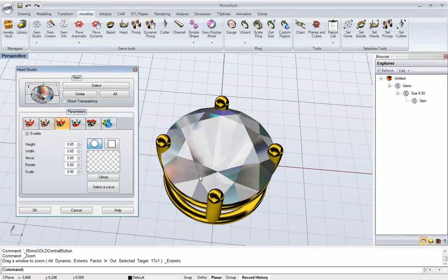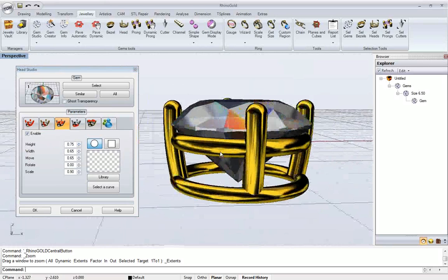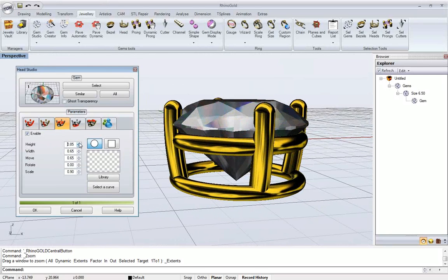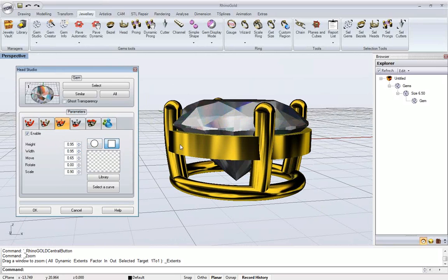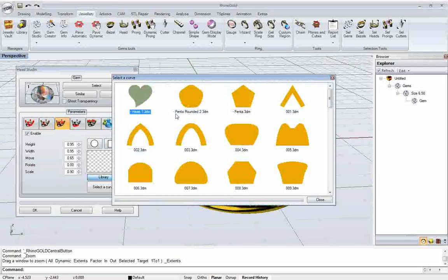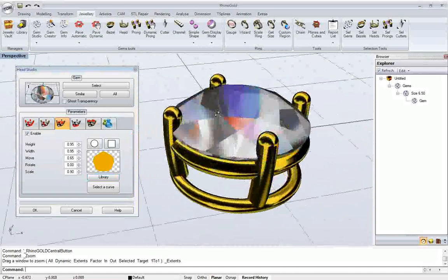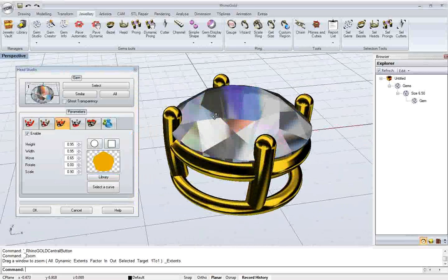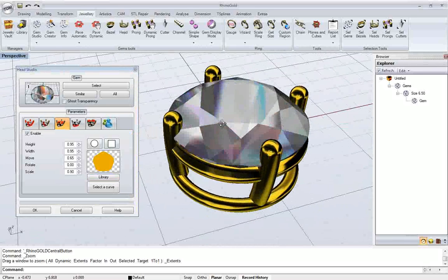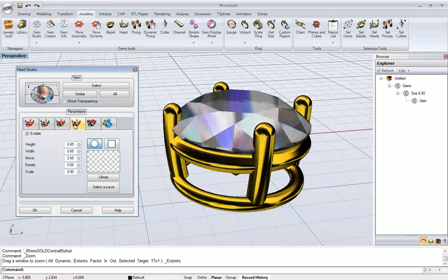Great. Then in the first tab we can modify the rail. Okay, the top rail. We can modify the height, the width, okay, the shape. Now it's rectangular shape. Okay. We can come to the library and select other curve. Okay. One important thing of the library, this library contains 3DM files. It means we can add our own files here. Okay. Great.